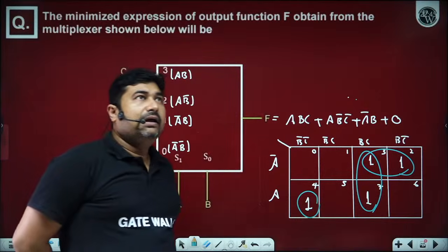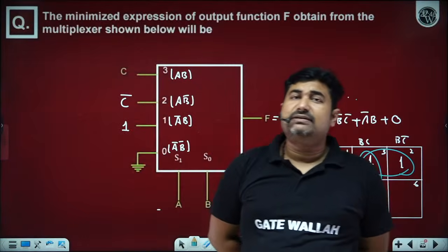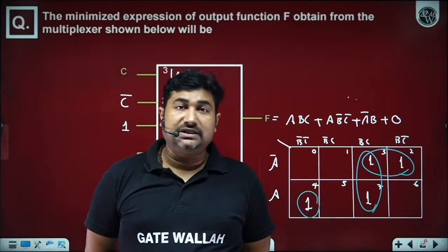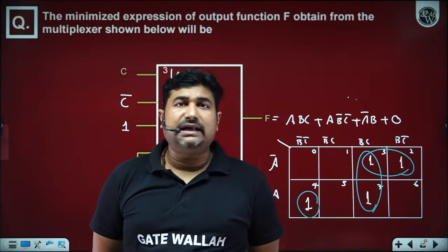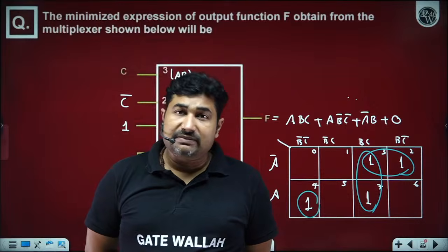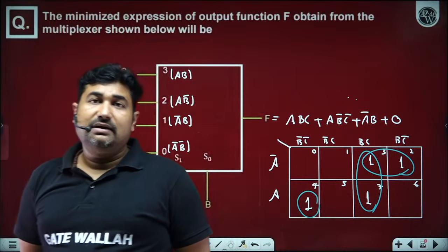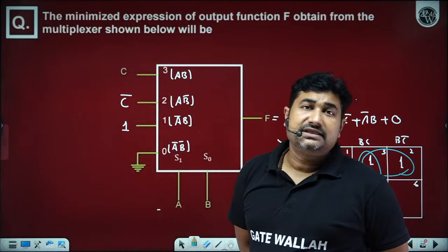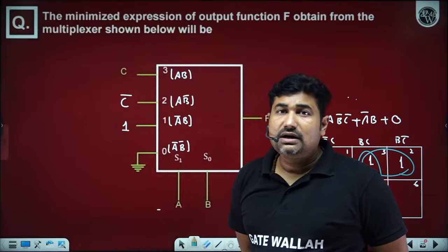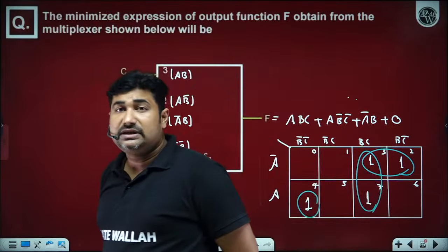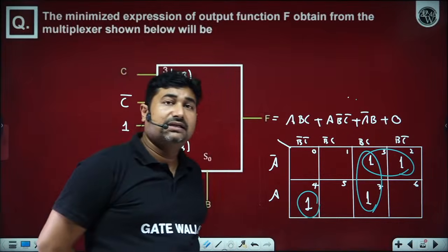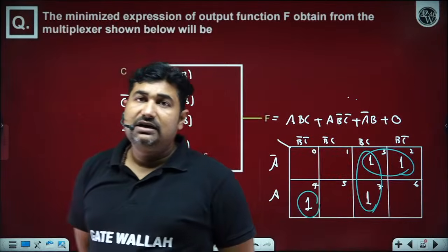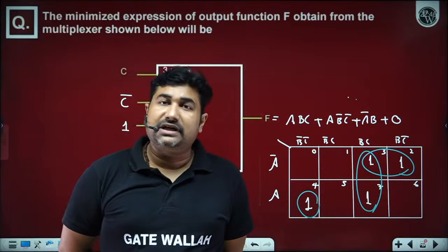Great. Actually, we can implement any function by using a multiplexer. Mostly, whenever we have to implement a function, we have the variable and its complement available, because when the data is coming from memory, that is bistable multivibrators, under that condition we have both the variable as well as its complement. Is it okay? So in such cases, if we talk about sizes, then the best size for the multiplexer is such that the number of select lines is the total number of variables minus 1, theoretically.